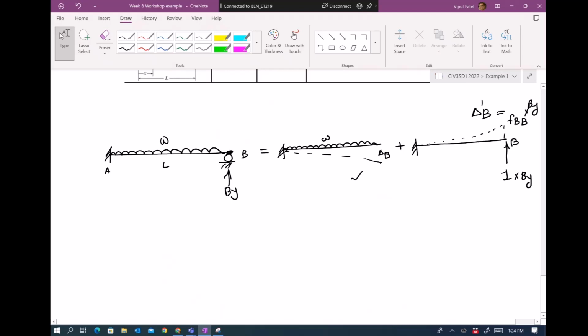That you have this deflection, and then we can find By. Once you find By, then most of the problems are solved. Right, so let's do that. One is done. Look, these force methods are quite simple. Only challenge is to find the deflections. If you know virtual work methods and find the deflections, others are just making those two deflections equal and finding the unknown value. So you understand the overall concept, right?